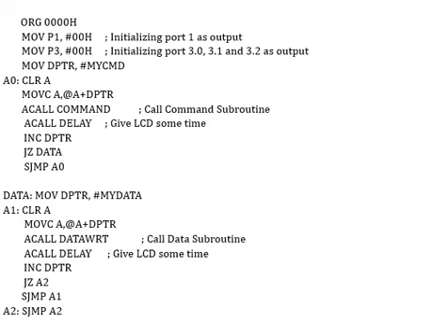data. So similar to the command subroutine, this data subroutine is there where you are going to call the data write, then call delay to give some time, and increment the DPTR similar to the command.